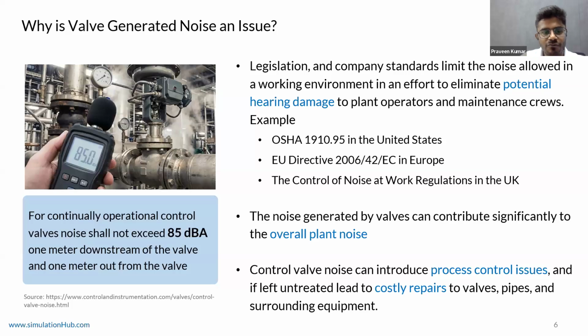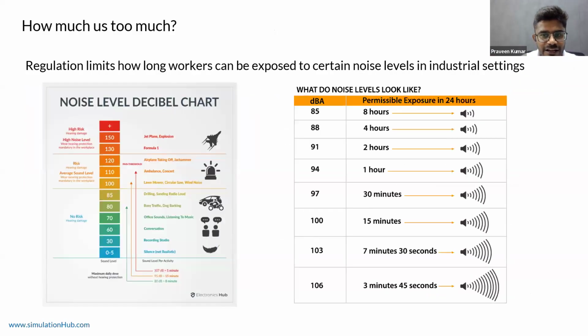It is measured 1 meter downstream of the valve and 1 meter away from the valve. So what does 85 decibel feel like? You can see on the left over here. Let me take the pointer. You can see 85 decibel sound is something like this, and it is at the border of no risk. When you go slightly above, even 1 minute of exposure at 107 is a risk, and above 130 it is high risk.